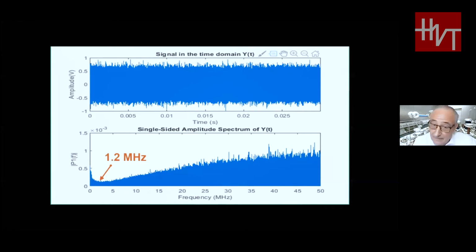How to do it? It is not easy on-site, because the best way is to remove the high voltage in order to have only noise, but it's not realistic. Probably the best way is to place the sensor very close to the real position. The real position of, for instance, a high frequency sensor is clamping the conductor that connects the termination with the earth.